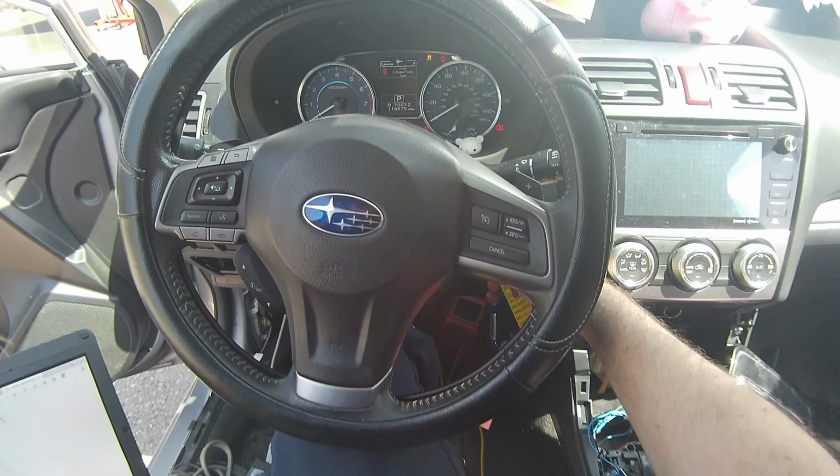Turn the car on. This is the solenoid in question. It is plugged in, and when I step on the brake, it doesn't move. Okay, it should be going in and out, in and out, in and out. What should be happening is when I step on the brake pedal, it should go in, out, in, out. Okay, and it's not doing that. That's all the movement I'm looking for.